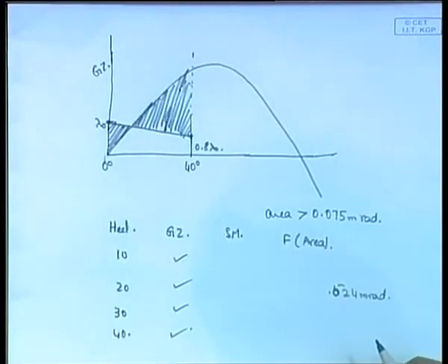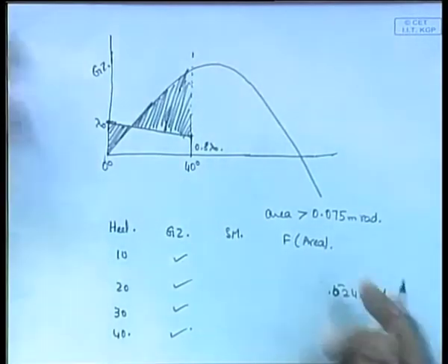And let me check this, I think I didn't explain it properly, something I missed here, wait. The residual area between the heeling arm curve and the righting arm curve up to the angle of maximum difference or the angle of flooding should not be less than 0.075 meter radians.